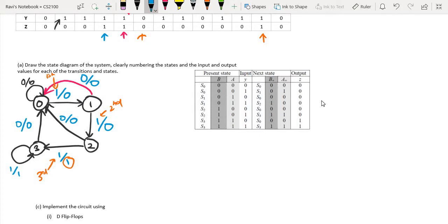Again, this is with 4 states. If you use 3 states, it is also possible, but then you have a don't care state, which you probably need to check, to see if after you do your reduction, it comes back to a self-correcting circuit, as you saw in your tutorial.